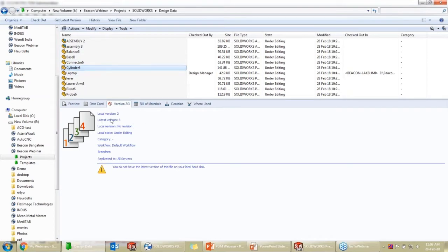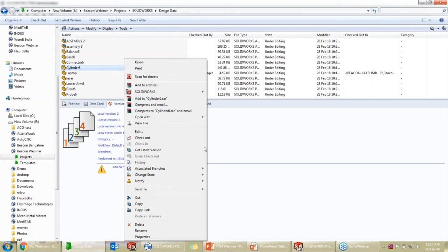So previously, I told you there is something called a workflow. Through the workflows, we can stamp the revision as and when necessary. So moving forward to versions, any changes that are made and put into the server will be captured as one of the versions. So these versions are cumulative data that are being stored inside the server. So at any point of time, any user who has the permission on that particular file will be able to retrieve the previous data and then work on it.